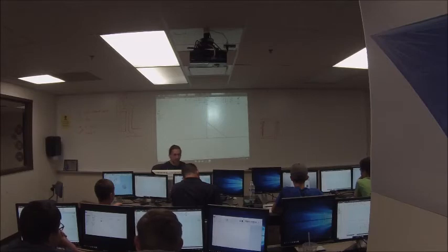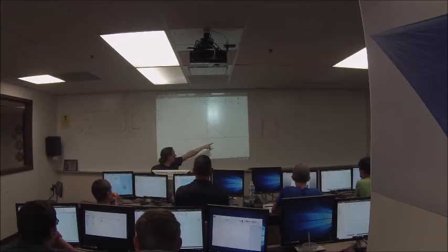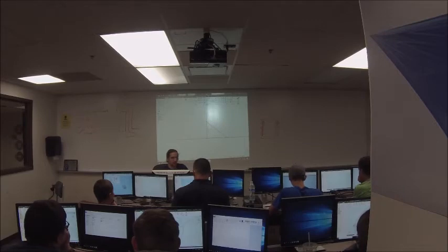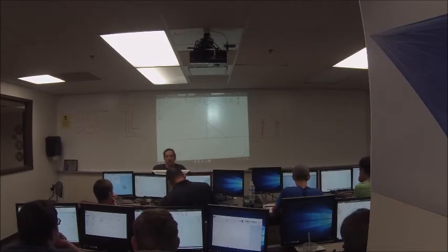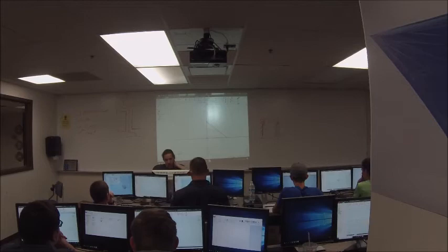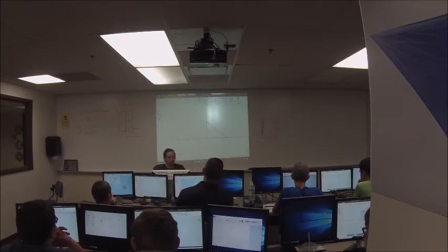Basically, if you press F8 on your keyboard, it'll show little icons everywhere there's a constraint. Now this sketch is not very complicated. You guys can put some lines on your screen if you don't have any, or you can watch me. I don't care. You can see here's a vertical constraint, and here's a perpendicular constraint. Now, I want this line to be horizontal, and I want this line to be at some other weird angle. So I need to delete both the perpendicular constraint and the vertical constraint because I don't want either of those.